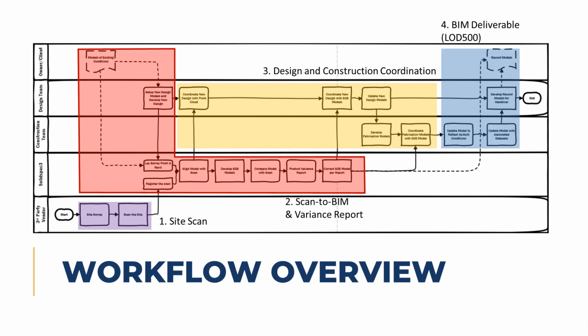Second is the scan to BIM development and variance report. This is the focus of today's presentation, and we will go through the details in the later slides. The third step is the coordination process, where the design team and the construction team leverage the scan to BIM models for coordination. And the last step is we incorporate the scan to BIM models, the as-built conditions, and all the metadata to develop the LOD 500 deliverables.